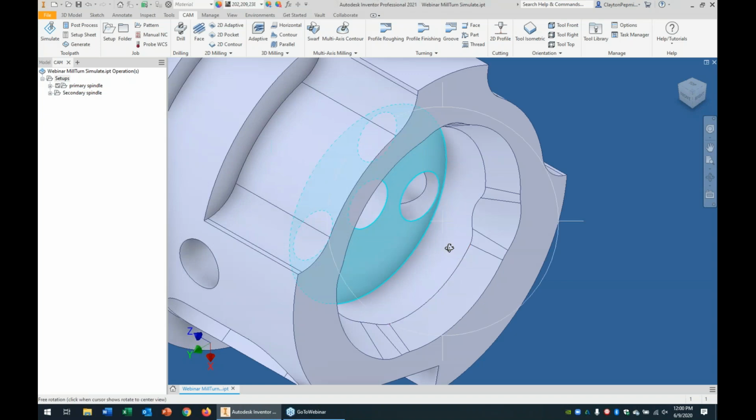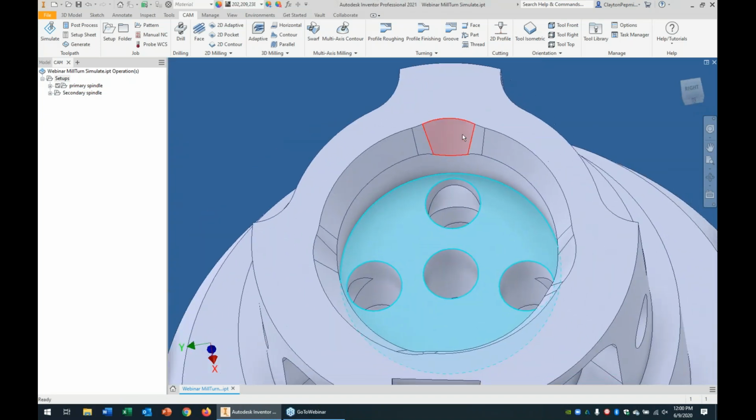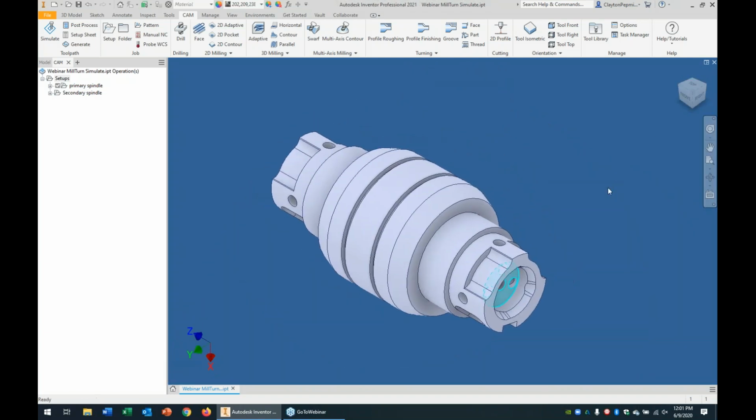And just to give you an idea of what that looks like. These little dimples here, it's basically almost like a chamfer, but they left a dimple to leave room for clearance for these holes. So not only do you have a chamfer, you got the little dimple. That is pretty much really hard to do without having full 5-axis capabilities. But that's why we used a 5-axis swarf here on the end, just to show as much capability as we could. And unfortunately, it looks like it's 12 o'clock and I'm running out of time.